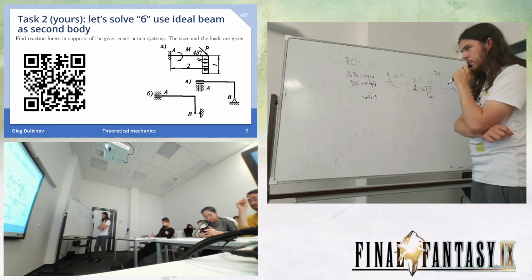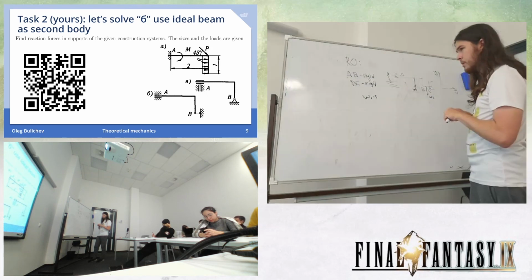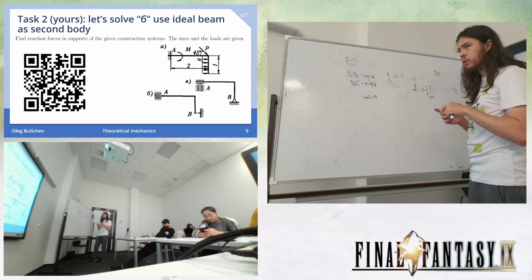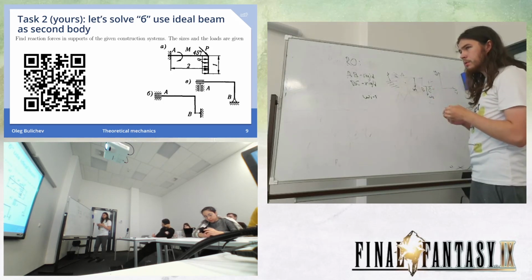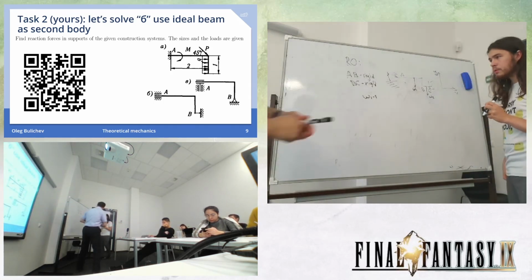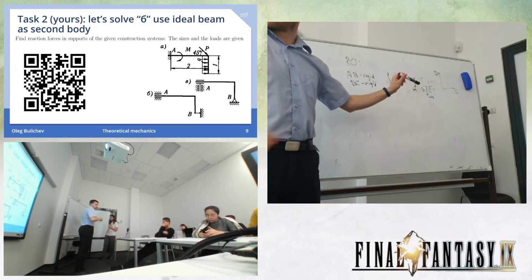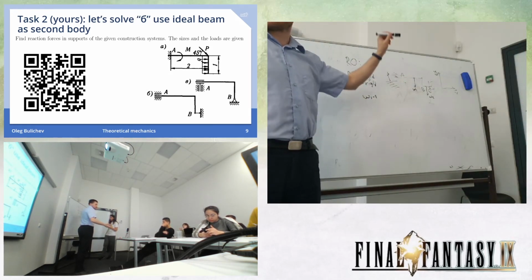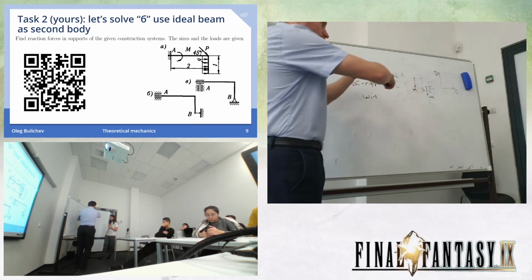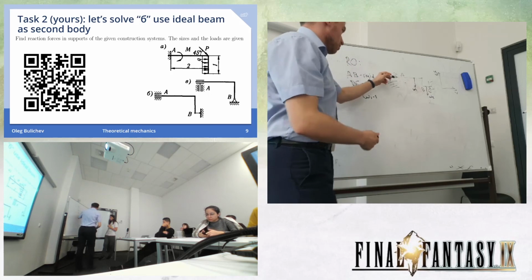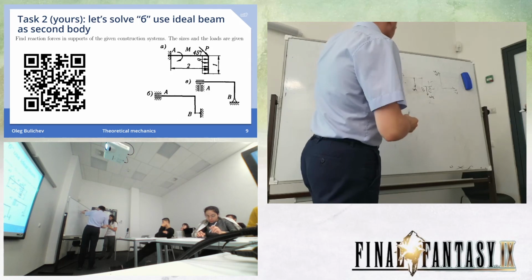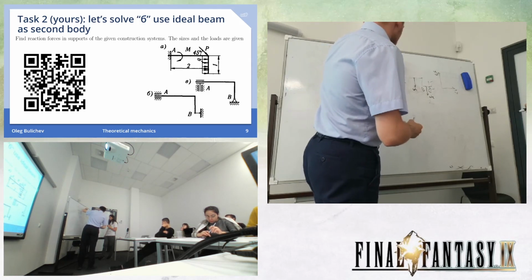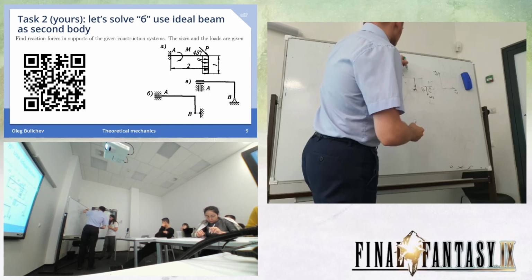Yes, because we have several axes and they apply to different points on our body. Because sliding cannot be bent. So again, probably some of you didn't get it. We have a slider. It can move in this direction, so we don't have reaction force on the x-axis. Can we just easily go up? No. Can we rotate it? No. So in this case you have Ry and MA.